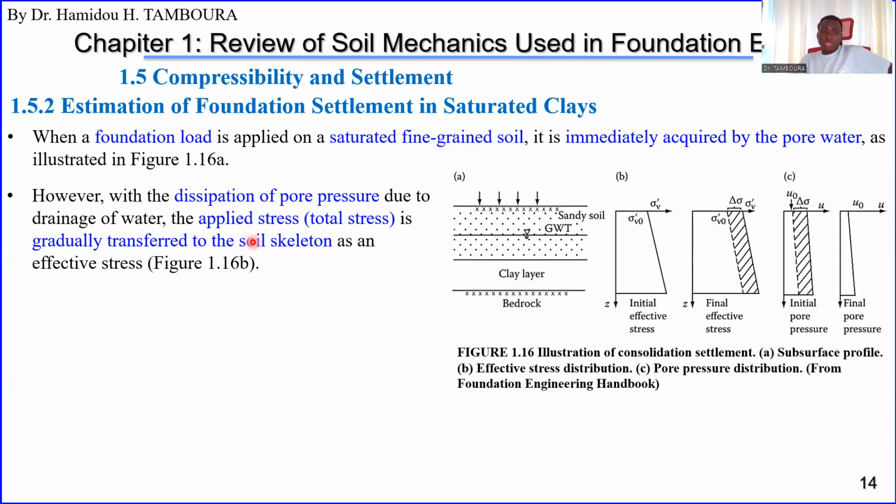So gradually, the total stress, the applied load, will be transferred to the soil skeleton, okay? Soil particles, as effective stress, something like this. So effective stress is the actual stress that soil particles are receiving. I think we have explained all this before, okay?